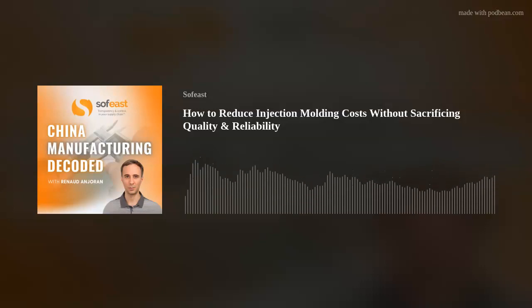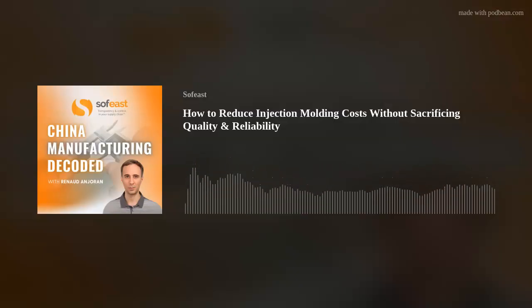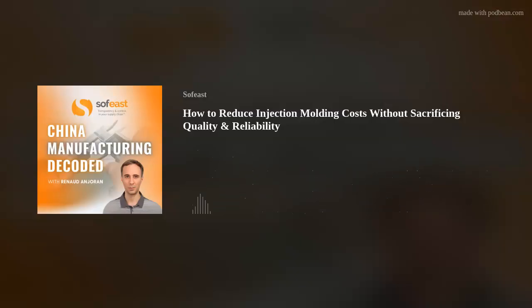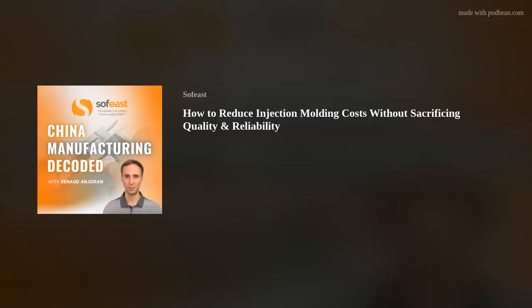So there's probably a few there that I've talked about in the part design and DFM. Now, if we're smart, all of these things will be picked up in the DFM and changed before we actually cut steel. Again, super, super important. As soon as you start cutting steel and then you want to make changes, price goes up. If you're making a change on the CAD, you haven't cut any steel yet, so it's all good. We're on the good side. So that's probably lever number one, let's say.